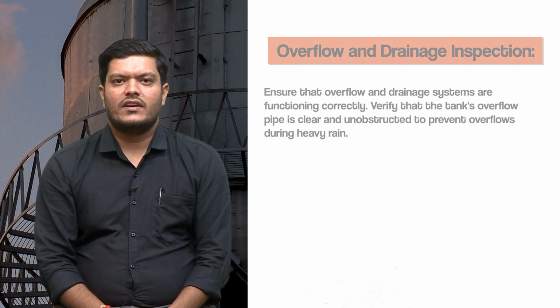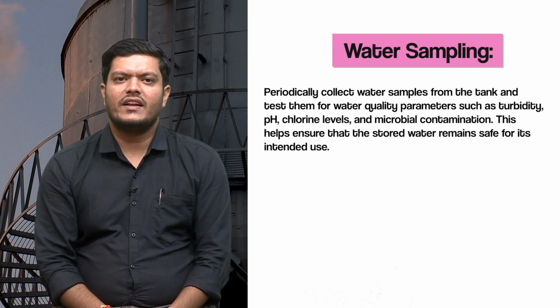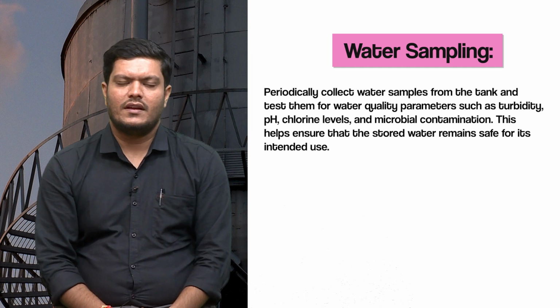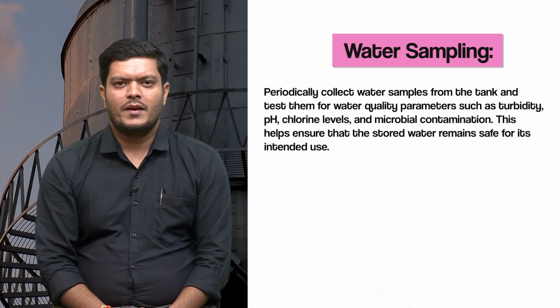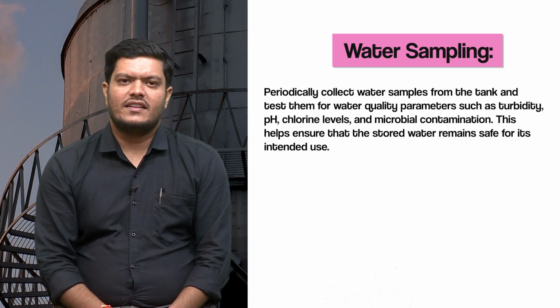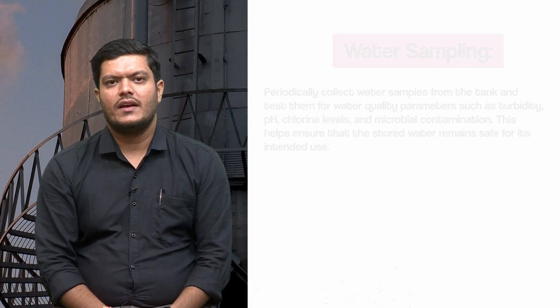Now the next is water quality monitoring. Water quality sampling: periodically collect water samples from the tank and test them for water quality parameters such as turbidity, pH, chlorine levels and microbial contamination. This helps ensure that the stored water remains safe for its intended use.